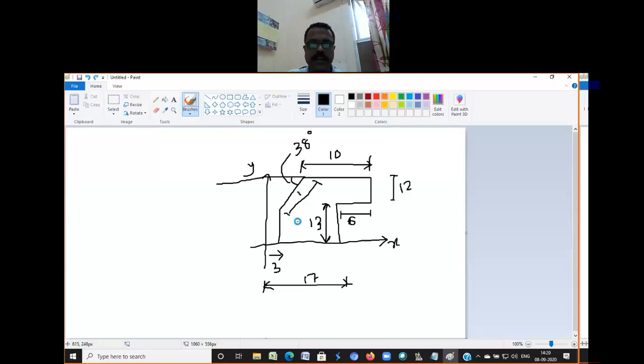Or I don't specify the length, so it's basically where this line and this line meet. So please draw this figure, and in order to draw it, use these commands: line, then offset, and what other commands you will need? Trim. So 1, 2, 3. With these 3 commands, I think you can draw this figure.